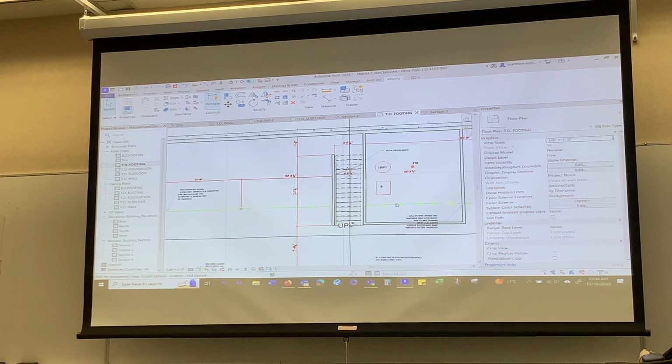I'd go to hidden line, because it's really hard to see what's going on there. Make sure you're working in fine, you're working in medium right now. You want to see your drywall and everything. Okay, so click on the stairs. Click edit. Click edit stairs. What do you want to do, make them wider? Yeah, so click edit stairs up top, and you'll get your handles. You have to scroll down to get them, unfortunately.